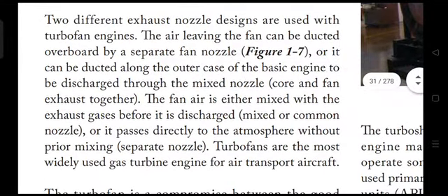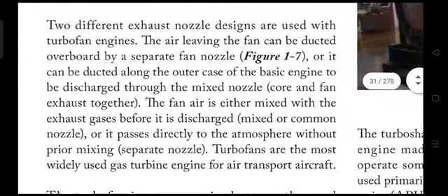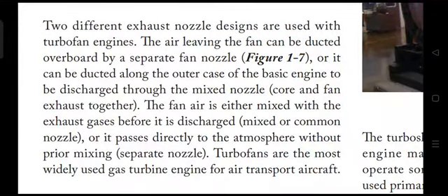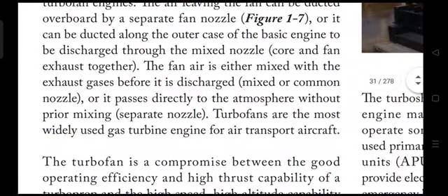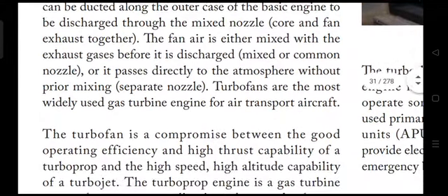It is not the fan or the propeller. It is the basic core engine. Now there are two different types of exhaust nozzle designs used with turbofan engines. The air leaving the fan could be ducted overboard by a separate fan nozzle, or it could be ducted along the outer case of the basic engine to discharge through the mixed nozzle.